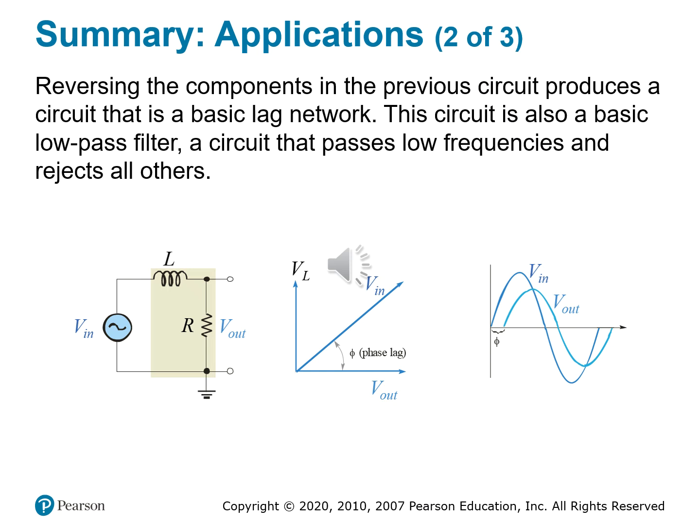The phasor diagram and the waveform on the right illustrate V sub out lags V sub in, and the output waveform appears slightly behind the input, especially as frequency increases. This is the inverse of the phase lead seen in the high pass configuration. And this is useful if you want to smooth signals, if you want to remove high frequency noise from analog circuits, or if you want to apply delay or to attenuate fast changing edges in digital processing.